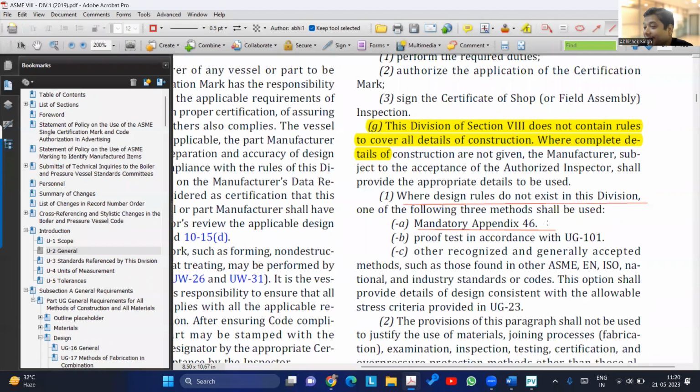Getting it? So can I use FEA for derating again? No, we cannot use FEA for derating, because there is no jumping if the rules are available. If by Appendix 2 we could not pass, failing does not mean that you can jump. The first clause is not saying that if the component is failing using these rules, then you have to go and use Division 2.